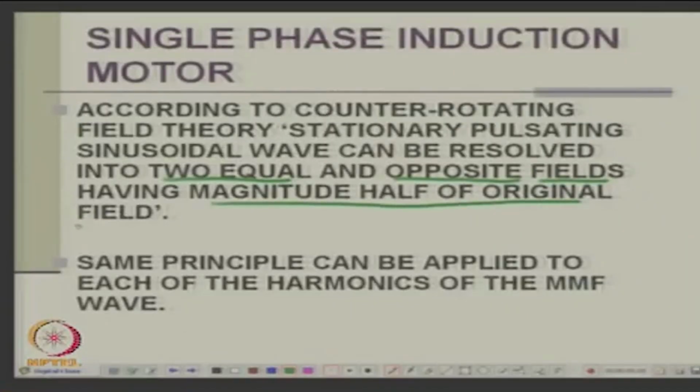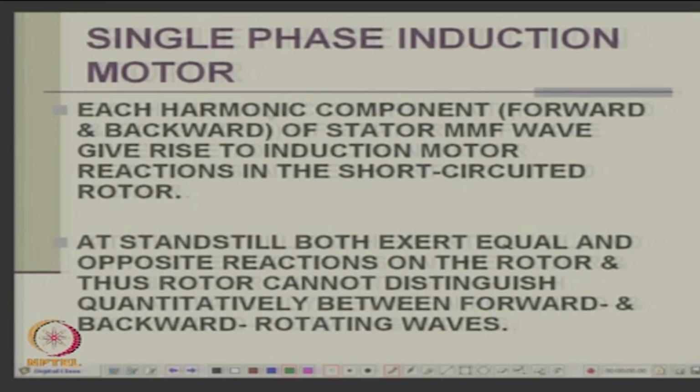Now, hopefully we are clear that a stationary pulsating sinusoidal wave can be resolved into two equal and opposite waves of half the original magnitude, and this will also be true for all harmonics. So, each harmonic component, forward and backward, of the stator MMF can give rise to induction motor reaction in the rotor.